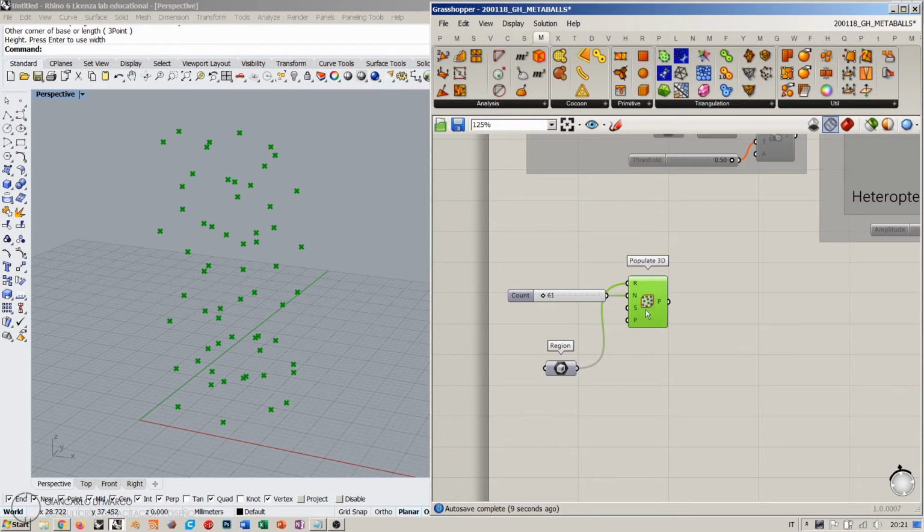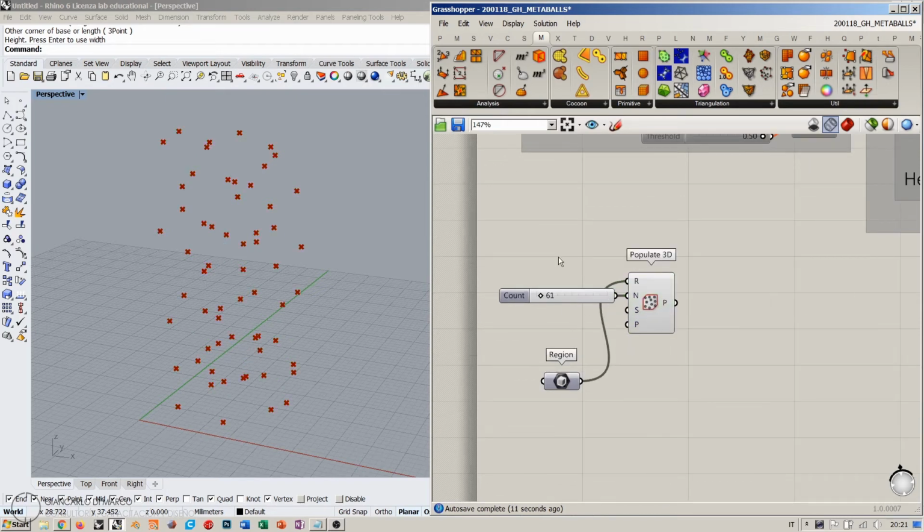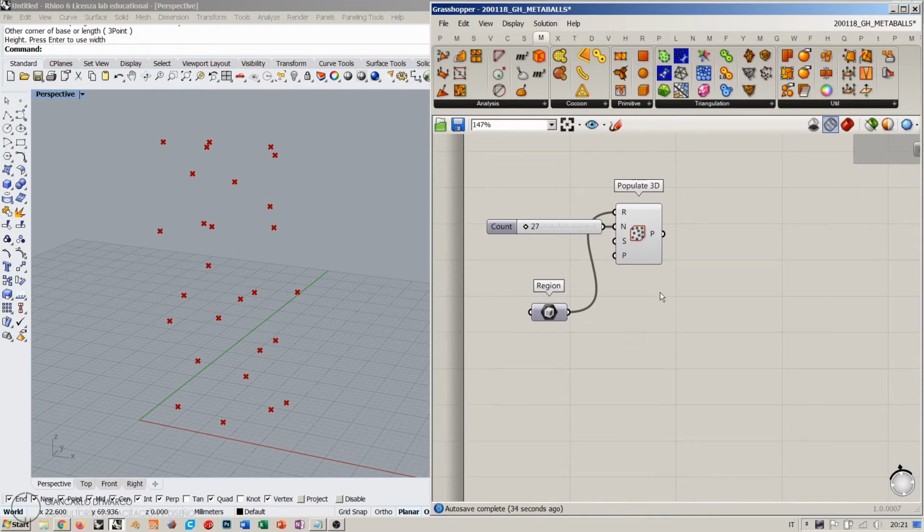Just remember that in Grasshopper, if everything works fine with a few geometry, it will work as well with lots of geometry. The only difference is that you are stressing the computer way too much, and eventually it might crash. So I always recommend to my students that they lower the values of the sliders unless it is strictly necessary to work with lots of geometry.